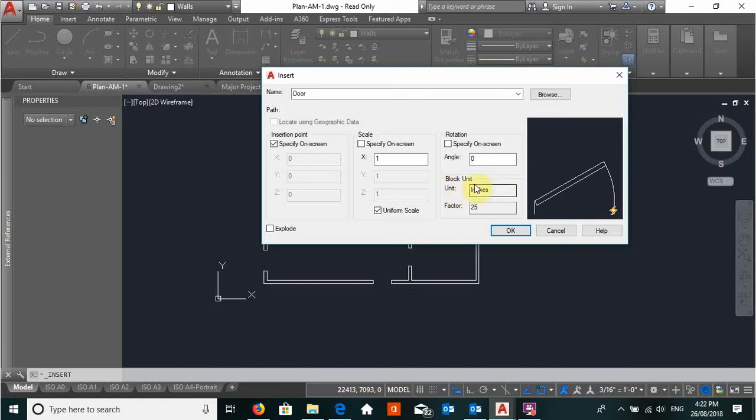So what I will also discuss is looking at blocks with the tool palettes, and that is a dynamic block, meaning that this is seen as a universal block throughout AutoCAD users, but we have the opportunity to manipulate certain features on here to suit our drawing.